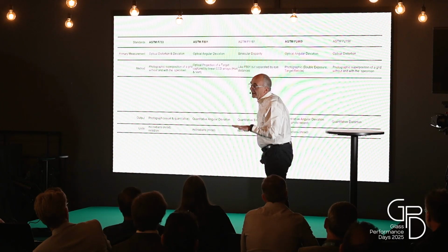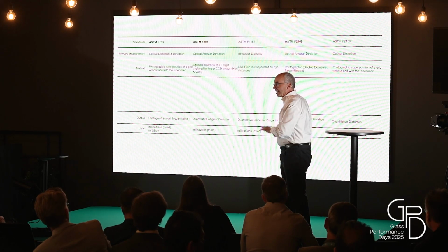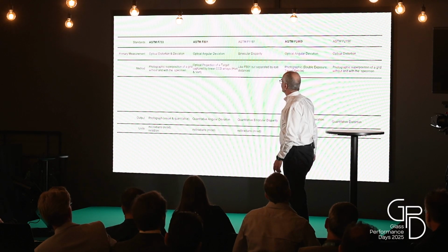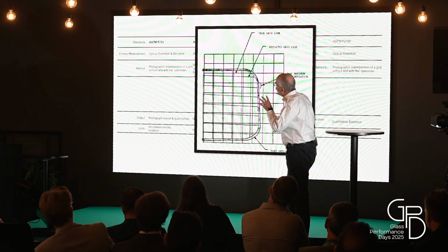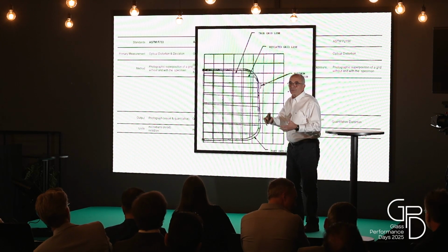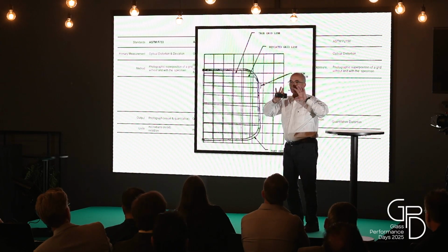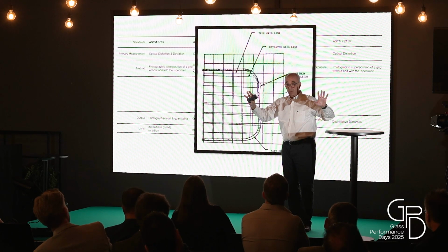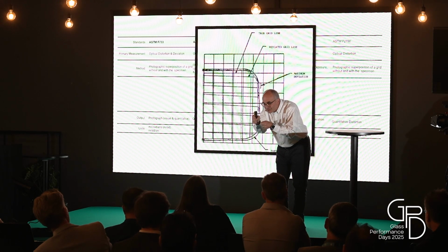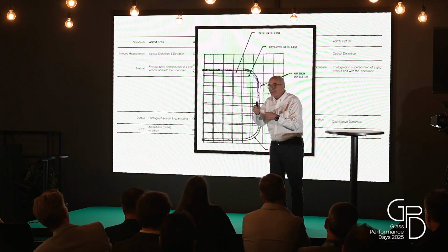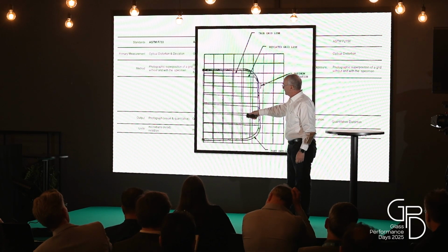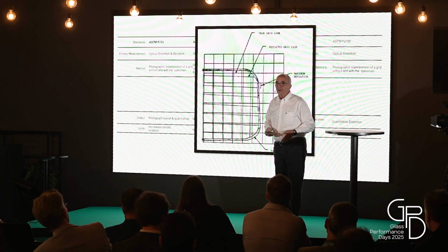So here you have 5 different standards, and I'm going to go through that rapidly. Basically, they pretty much work the same way. So the fundamental one is the 733, where it was initially done with photographic film. You would take an image of a grid without a windshield, and then superimpose the second image, and then on the picture you would measure with a measuring tape. You would measure the distance of the deviation and deduct the milliradian deviation of the ray.